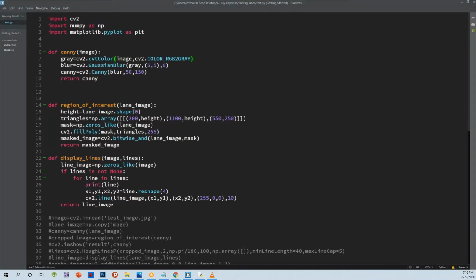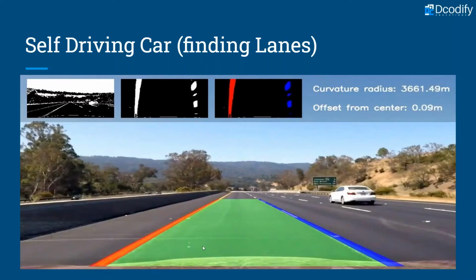In the self-driving car industry, finding lanes using computer vision, step one is to convert the whole colored image into a grayscale image. Then we obviously need to reduce the noise, and we can use filters like a Gaussian filter in image processing. After that, in the system, we need to determine what lines or pavements we have, so we need to determine the edges in the image.